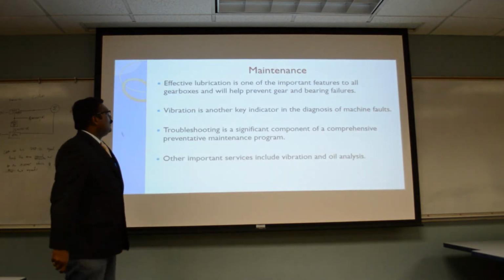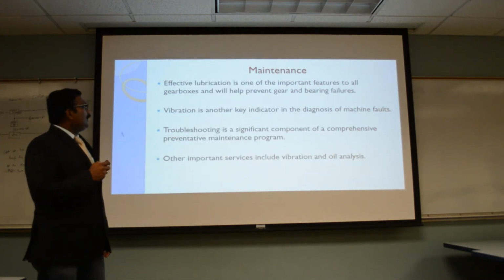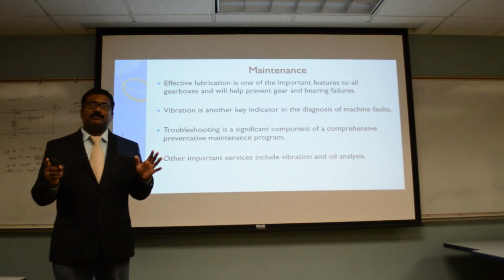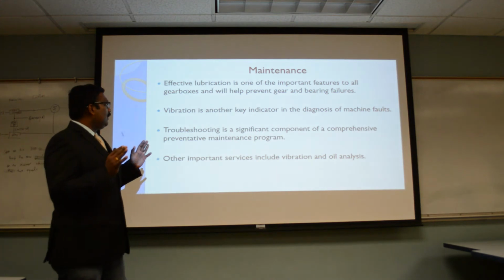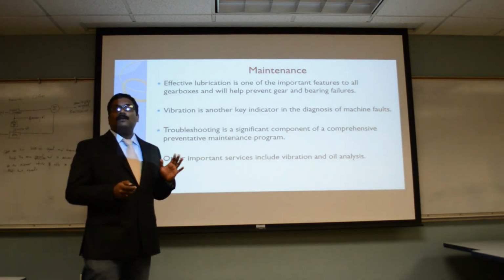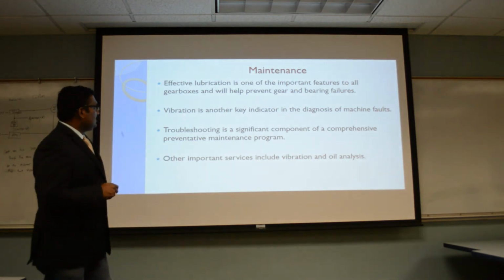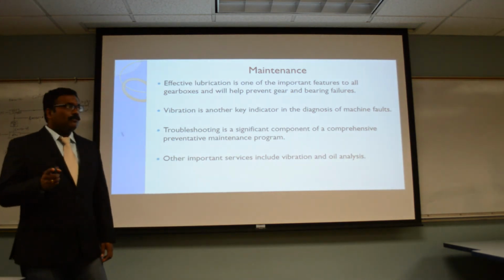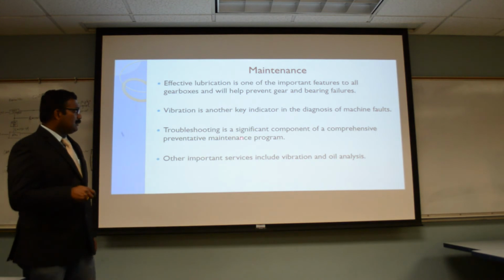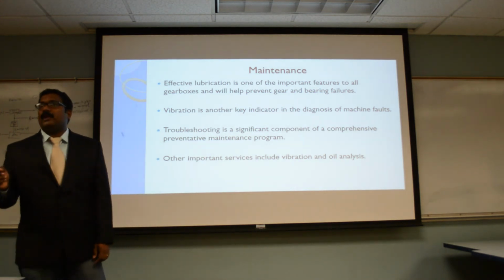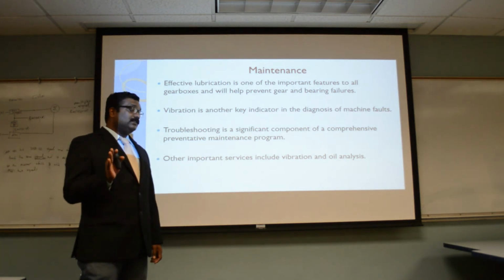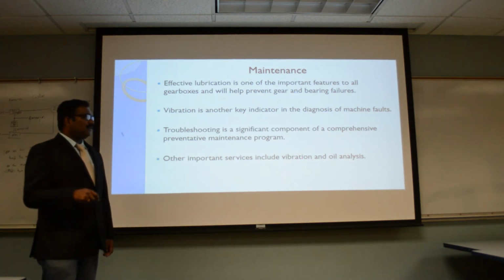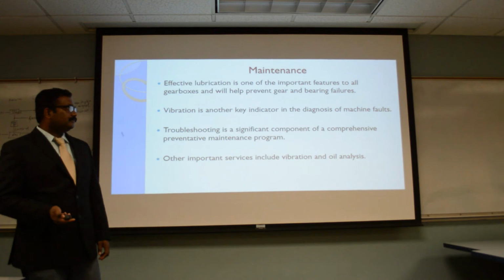The maintenance for the gearbox system. Effective lubrication is one of the important features for all gearboxes, and will help prevent the gears and bearings from failure. Vibration is also a key diagnostic of machine faults. Troubleshooting is a significant component of a comprehensive preventive maintenance program. Other important surveys include vibration and oil analysis.